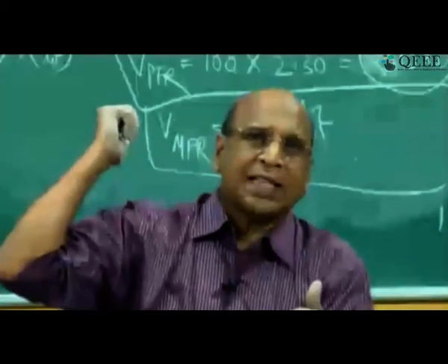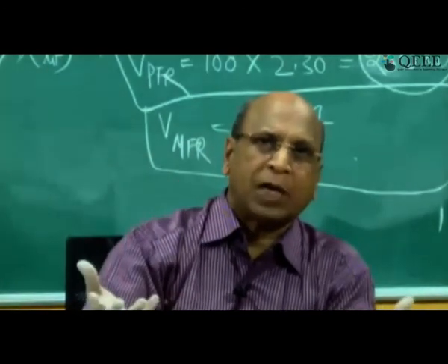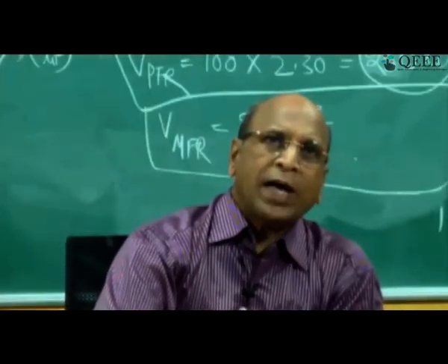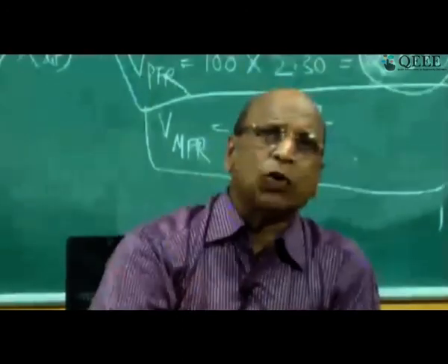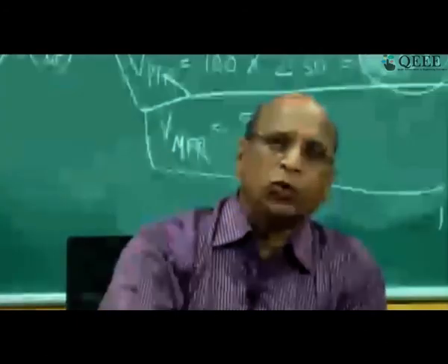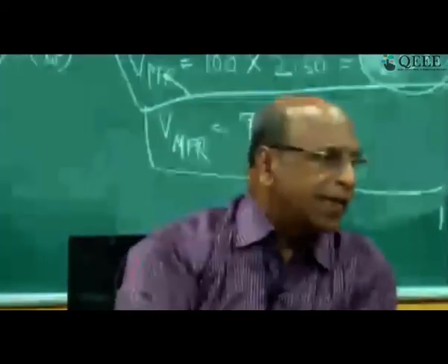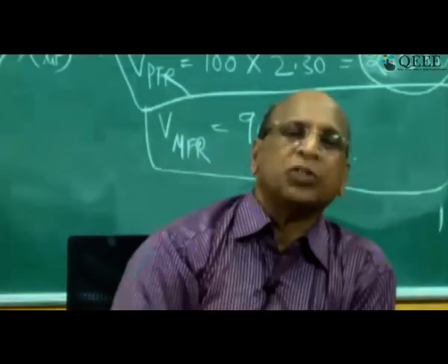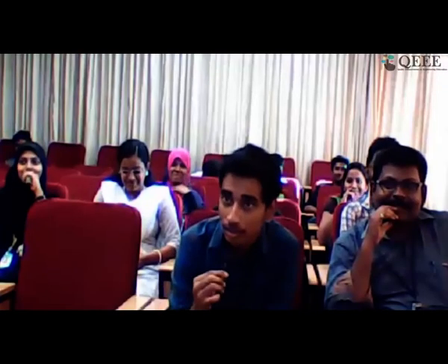If you see the design expressions, except in batch reactor, the time comes. In the other reactors, there is no time coming, and directly the volume comes. And what we are interested in is volume, not time. By the way, how do you design if I give you tau? Tau only. If you don't know volume by volumetric flow rate equal to tau. So that is why space time and holding time are not connected with batch reactor. It is only defined for continuous reactors. Okay? Thank you.